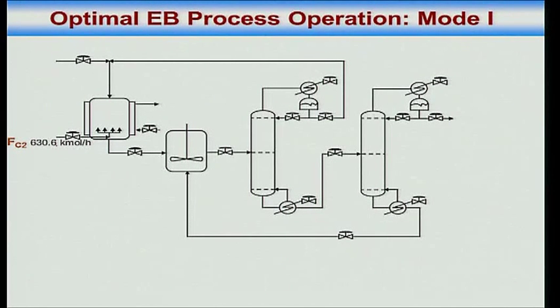So if I look at the active constraints, reactor 1 should be operated at maximum level, at maximum temperature. Reactor 2 should be operated at maximum level. Also, the impurity in the product should be at its maximum allowable limit. What is the impurity in the product? Any C6, any benzene that leaks down here will be guaranteed to end up here, plus whatever split is done by the second column.